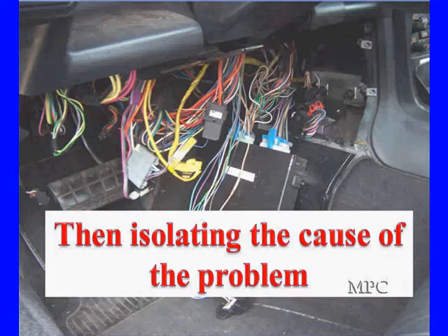Now, one of the reasons we're showing you this picture at this particular point in time is I want you to realize this is not a quick one-hour diagnostic. If you're going into this with a notion you can diagnose communications problems in one hour, stop right here. You're not going to get there. This was a vehicle we had to capture and thought the picture's worth 1,000 words. This is not uncommon to see when someone is working on a vehicle that's been in a collision. The dash looks like this, because we have frequently broken wires in damaged modules. So this is not an uncommon picture.